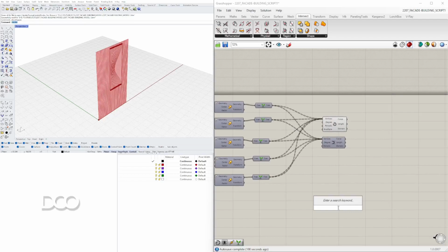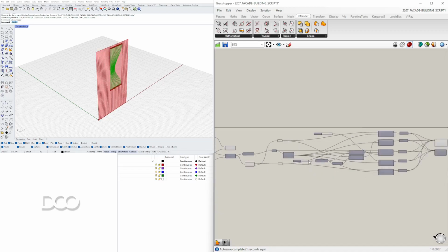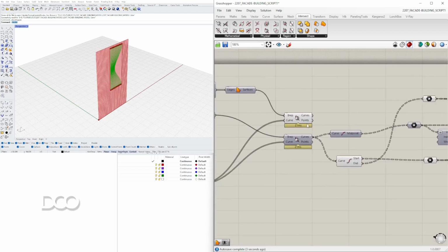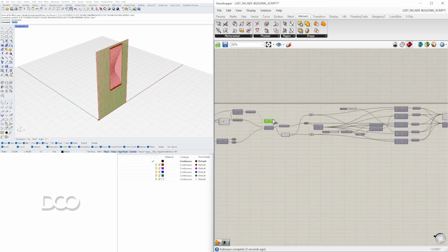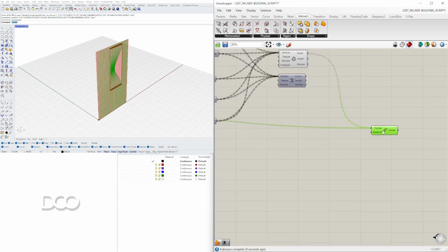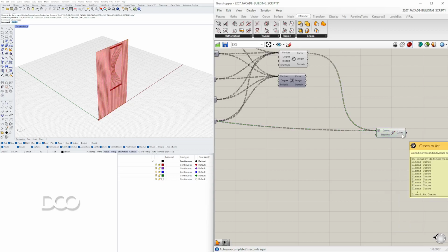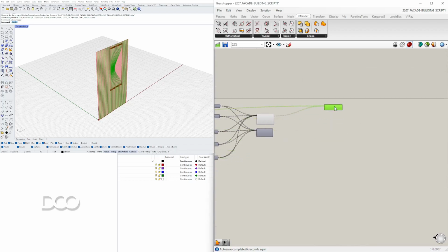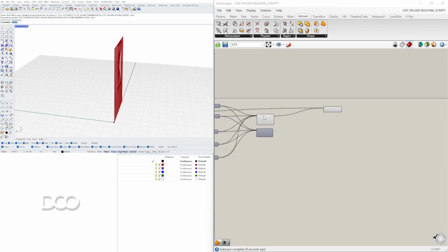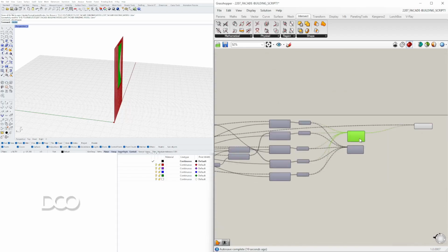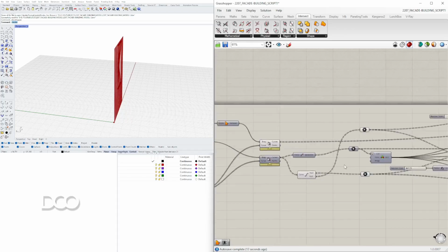Now let's take both of those inputs and we'll bring in a join curves. We'll plug that first. Then we'll go on to get the outside portion of the region. So holding down shift, I can add those in, and then I'll flatten the input. This way, when I see on the output, we have 35 curves that have been joined. We can basically disable preview on the originals.